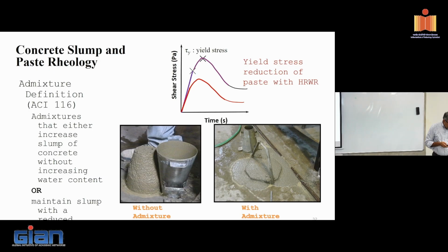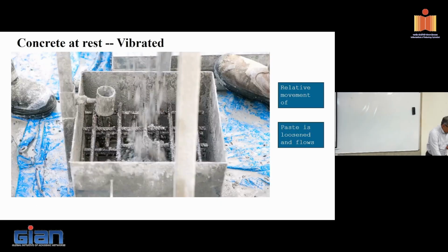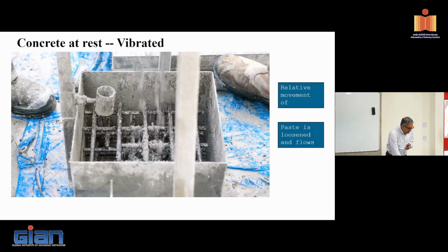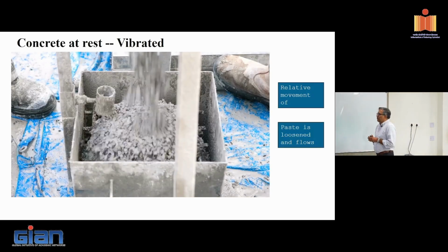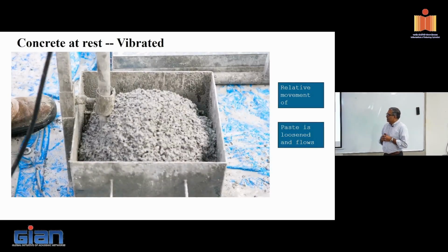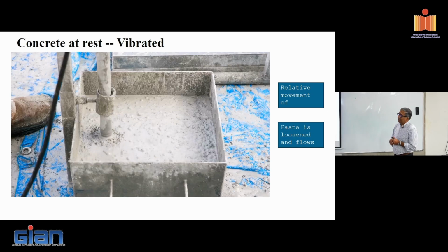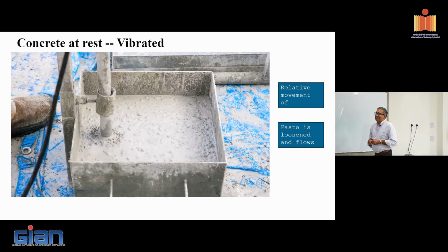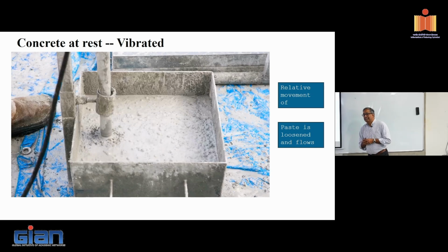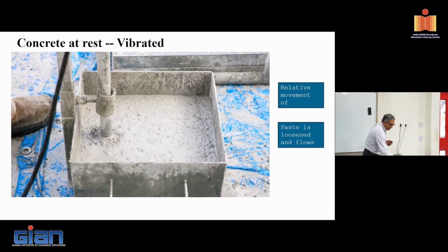Now, another condition of rest, which is what happens when we vibrate it. So we're dealing with concrete that looks like this. The minute we apply vibration, look what's happened. It just flows like a fluid. So what changes there then? Again, it was at rest. If you look at it, I just agitated it. So what happened when I agitated it?